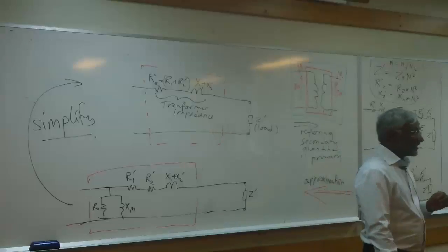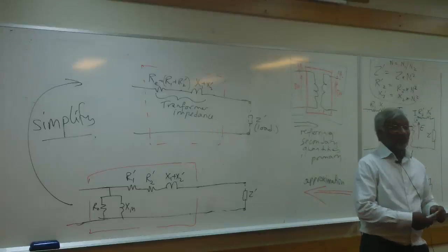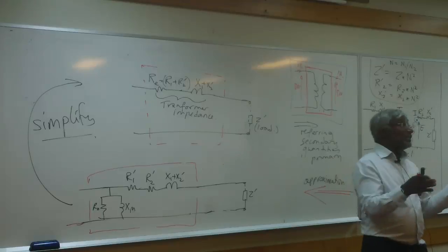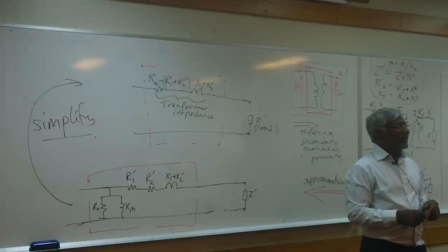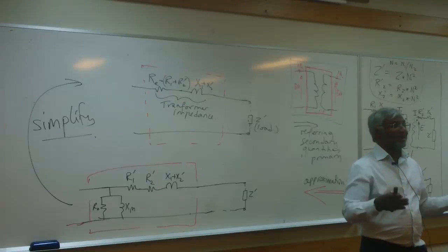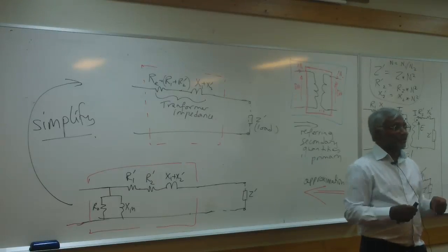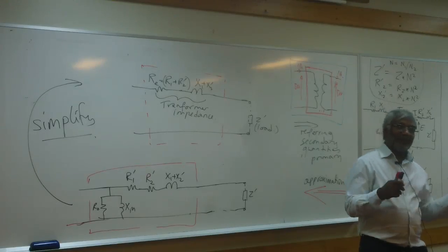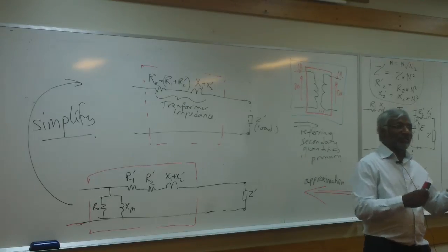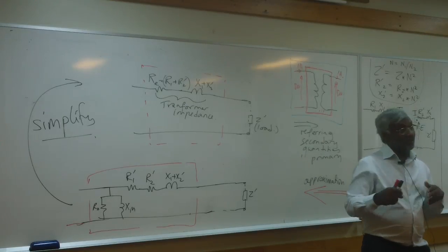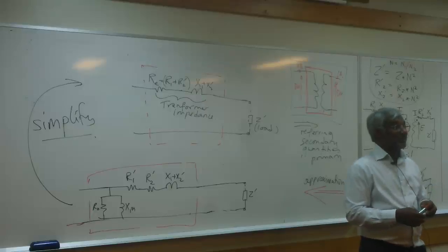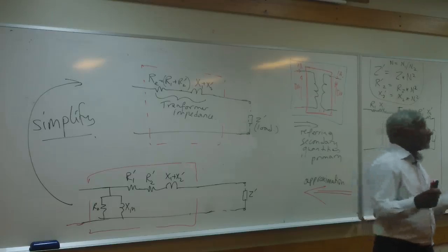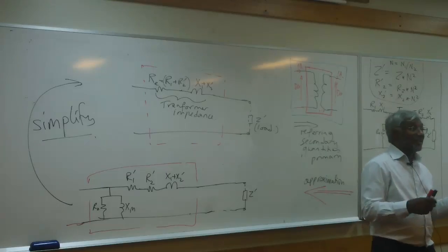Yeah, I'm happy you said that because I wouldn't have said that. So, yes, you may have to match impedances. Many times we connect transformers in parallel. Why would we connect big power transformers in parallel? We parallel them for redundancy. That means if one had a fault in it and was automatically disconnected from the system, the load is still supplied with the other one.